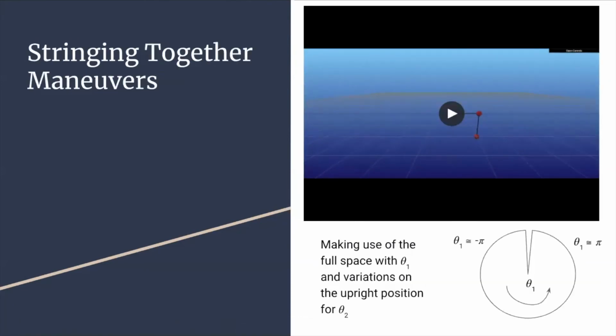Once we had trajectories optimized and stabilized using finite horizon LQR from any initial condition to the upright state, our focus turned to more complicated trajectories. For example, we have a trajectory here stabilizing every 9 degrees, alternating in the upright and down positions.